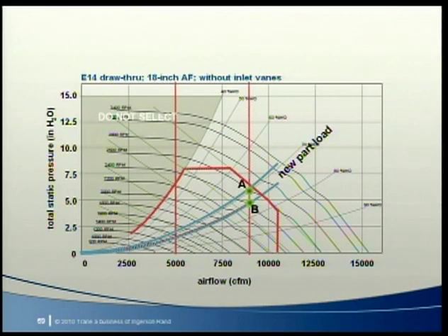Fan energy can be reduced even more by resetting the duct static pressure set point to keep one box nearly wide open. This lowers the system curve and the fan modulation envelope shrinks considerably. Sensor location isn't as important because its set point changes with load conditions. This approach reduces fan horsepower and prevents surge even at low airflows. We've discussed this kind of fan pressure optimization many times in the past, so we don't cover it in detail here. Just remember, it saves energy and Standard 90.1 requires it on many VAV systems.